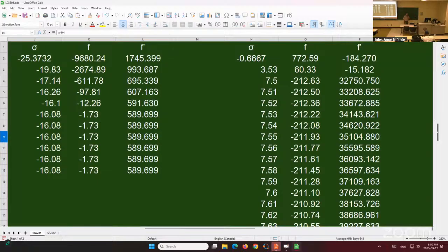So instead of covering a whole number of values for experiments, you do 2 initial tests, and you want to find the optimum value. So now you use the results of those tests to predict what should be your next test to get the 0 of whichever parameter you want, and then you can converge and see that you get it. So usually using the linear finite element analysis. Yeah, when you do finite element analysis, exactly.